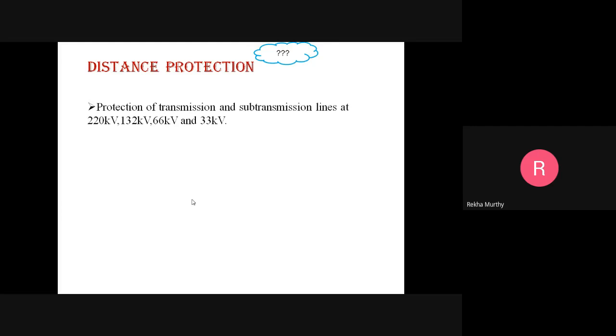For 132 kV and 220 kV systems, the recent trend is to make use of carrier current protection, and usually this type of carrier current protection operates under the control of carrier signals. Let us consider this distance protection scheme as a non-unit system of protection, where a single scheme provides both the primary as well as the backup protection.